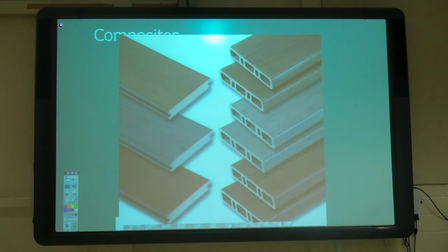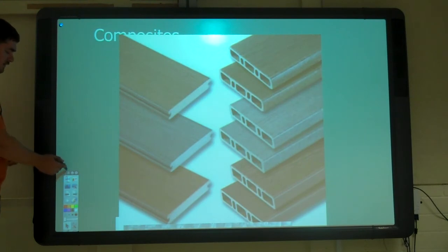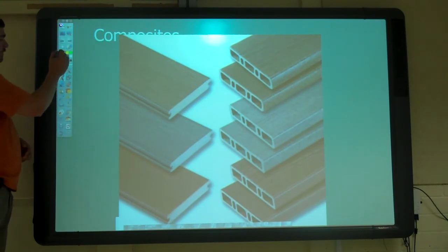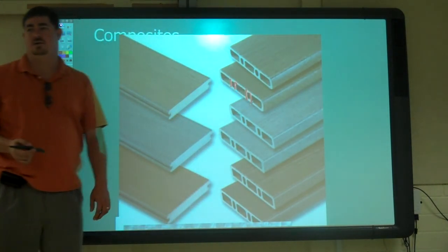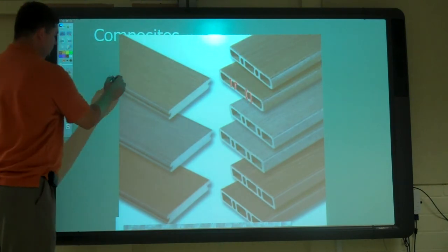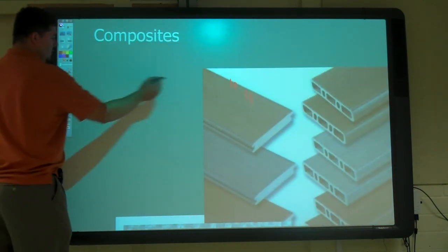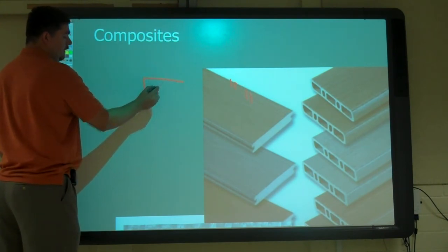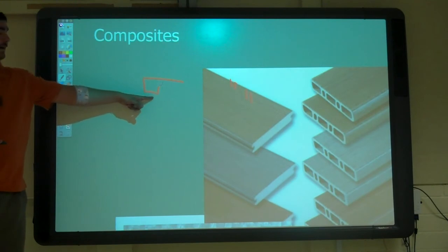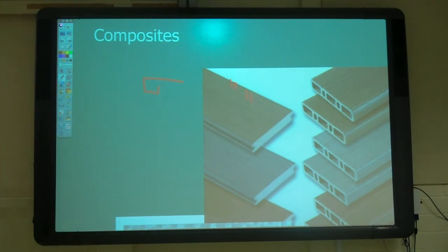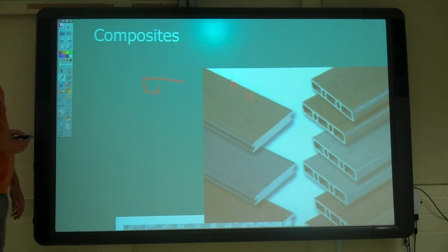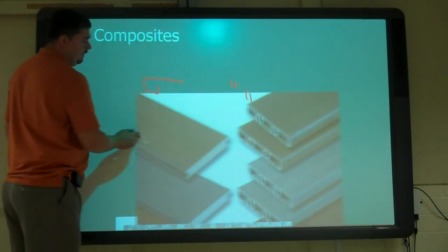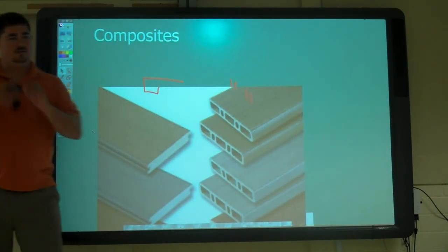If you've got something with thin walls, what makes it strong? Yeah, so anytime that you've got a rib, that adds strength. So like in sheet metal, bend, bend, bend like that. Each time you bend 90 degrees, you add strength to it. It might not look like that bend is doing anything, but it's adding strength to the whole thing. So they do the same thing here. Get some vertical supports in there, that adds a lot of strength to it.